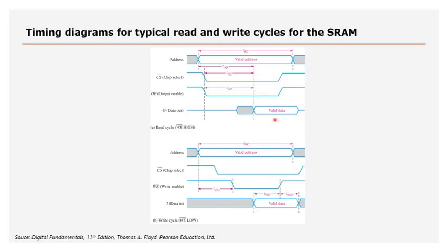So these are basically the read and write cycles of your device. But in a microcontroller, as you'll see in other presentations, a lot of these actions, like the chip select and the output enable, happen automatically. They are connected to the microcontroller, and happen as soon as you give an instruction, either in C or assembly. So you don't really need to worry about what's happening with these cycles.